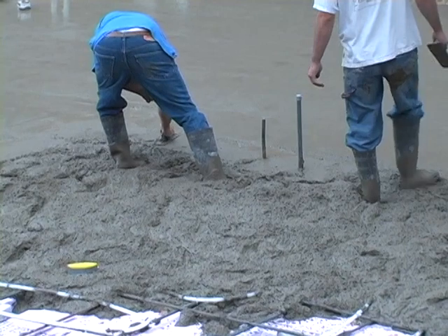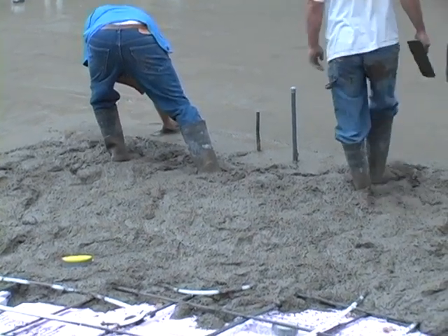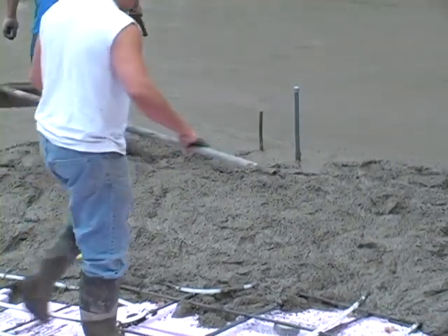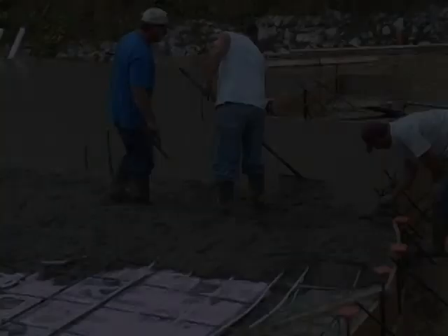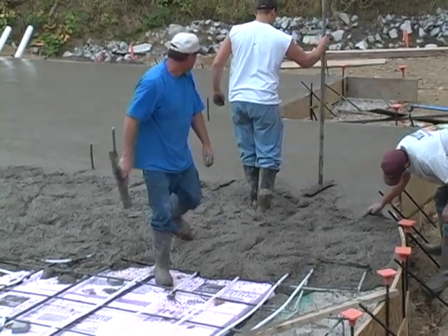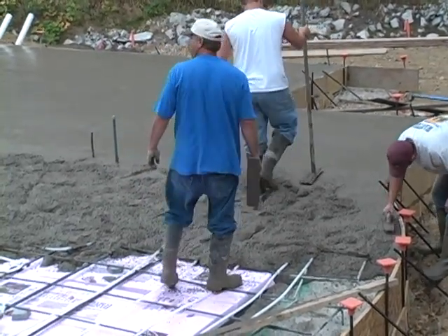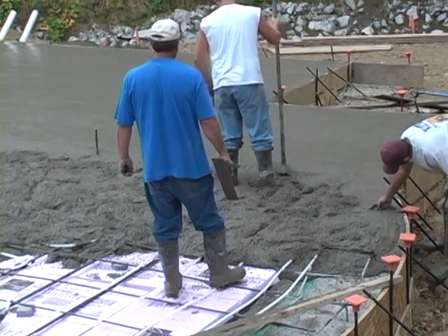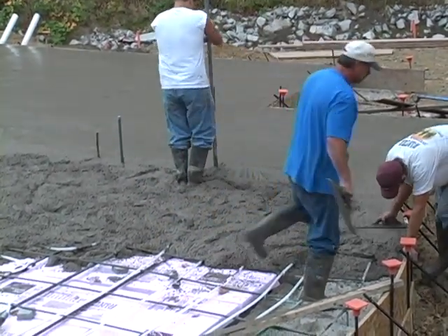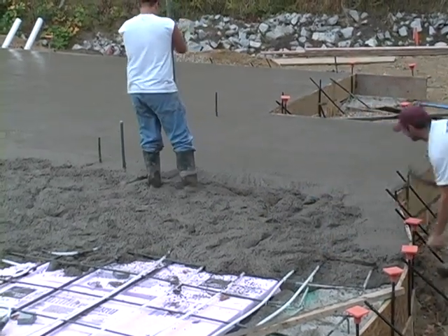and on the form board, if you're just getting used to this, you're going to want to run it against the form board. Again, once you get a little more skill, you won't have to run it on the form board. You'll actually rather use the mag trowel to flatten out along the form board, and then set your screed run on top of that. It actually gives you a little more maneuverability. You don't have to worry about hitting the stakes and so forth. It just makes it a simpler process all around.